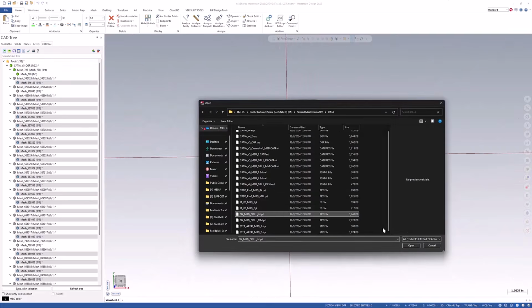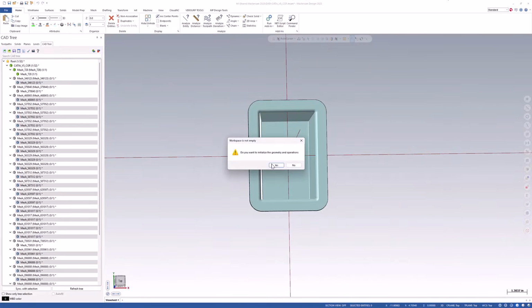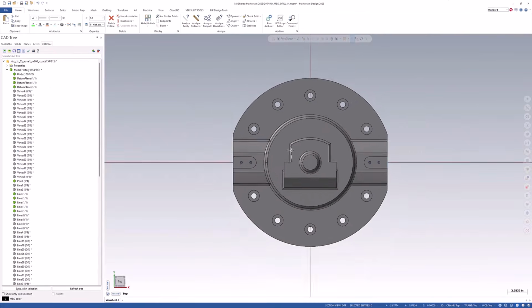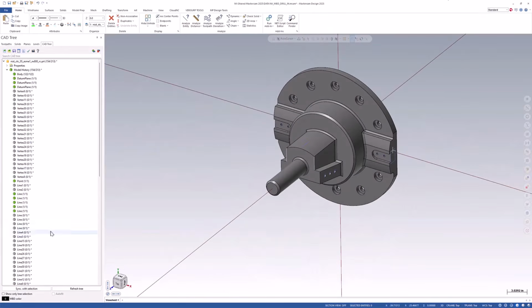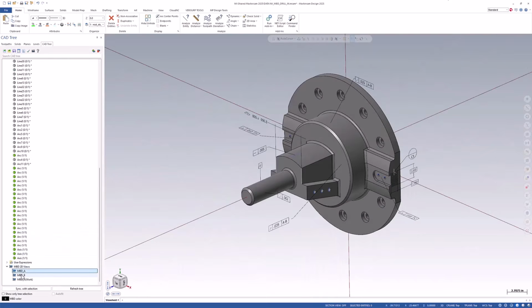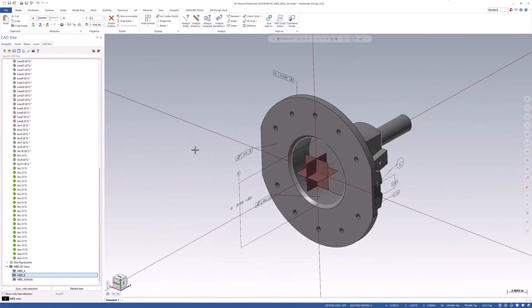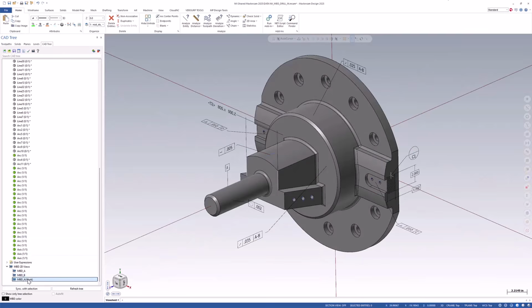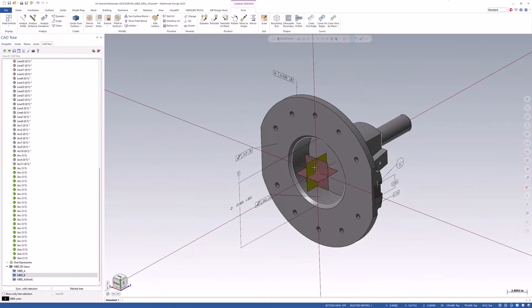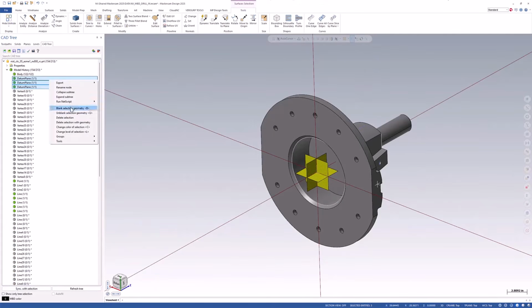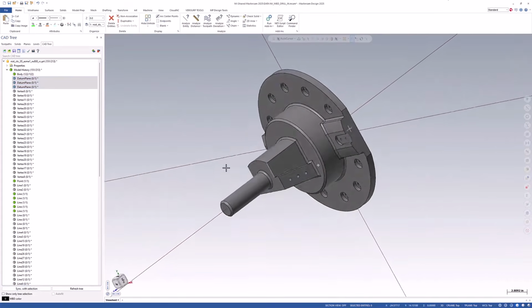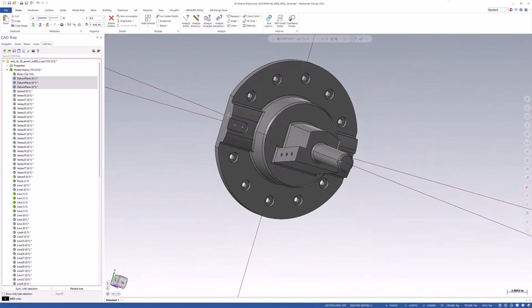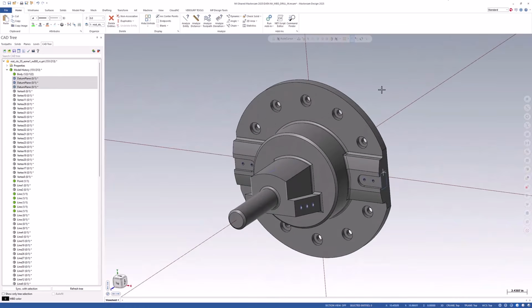And then another one would be a Siemens NX file. So same thing. We have our MBD data. We can take a look at different dimensions that are set up for this part. And if I have these sketch planes, again, I can quickly get rid of them, blank all that out, and then now I've got a bunch of geometry. And what's neat is that it integrates with Mastercam so well, and uses some of the tools that Mastercam has. You're not learning something new.